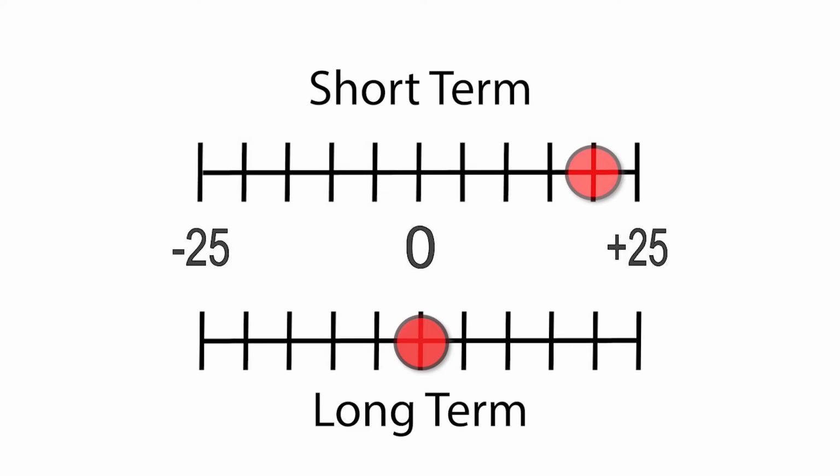Now, after a period of time, the long-term fuel trim will start to adjust to make the short-term fuel trim come back to 0. What's going on here is the computer is trying to make the short-term fuel trim have an adjustment that's real close to 0 as the long-term makes up the difference, if you will. But if you think about it, look here. At any given point, we can take our long-term plus our short-term and get our total fuel correction. At this point, I had stopped it at short-term fuel trim plus 10, long-term fuel trim plus 10, so 10 plus 10 is 20. We still have the same total correction as before.